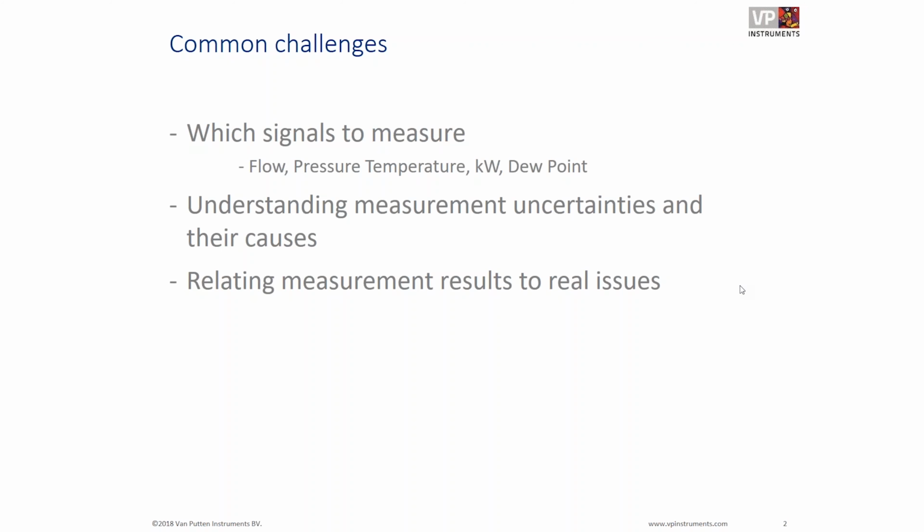So, common challenges with this. It's which signals should you measure? Well, Tim talked about that already. So you have to measure at least kW and flow, and also pressure. Temperature can also be very interesting, and in some cases, I would really recommend also to measure dew point.